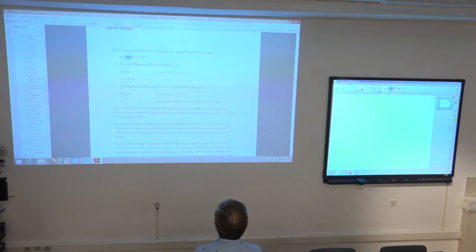If there is no argument for by how many bit positions to shift, then it comes from this SE register. So this SE holds the value. It says here SE was previously set to -3, which means this instruction will perform a right shift by 3 positions.